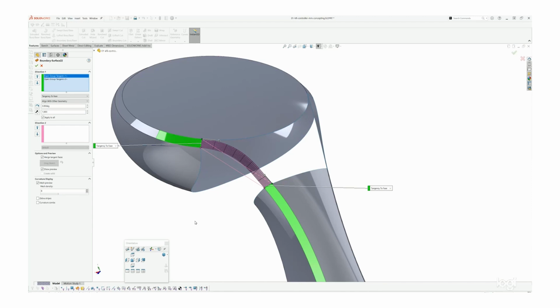And in this case, you can notice I don't have any second direction curves. I just have two primary first direction curves, and I'm deriving the shape just off of those two curves. Furthermore, I've also weighted one of the boundaries here. If you look at the first curve down here, it's its normal weight. But if you look at the second one up here, I've weighted it to be 1.5 instead of 1. And you can see as I continue to weight it, I'm changing my shape, but I'm changing in a very predictable way in what I want it to do.